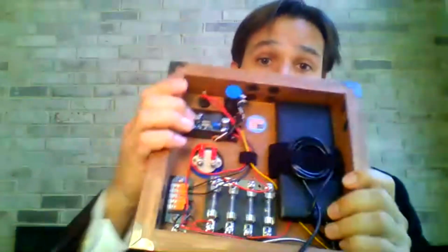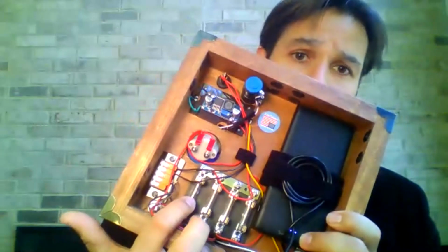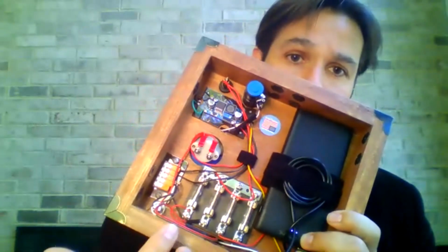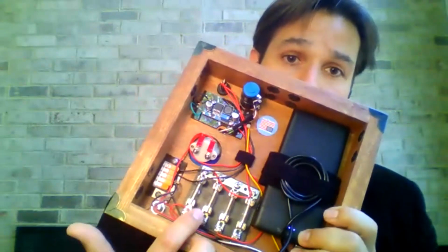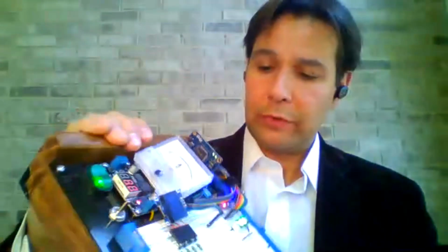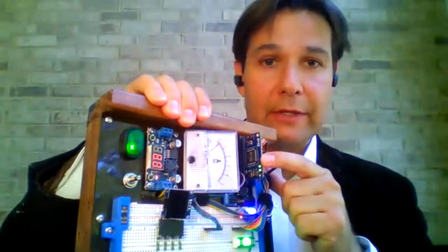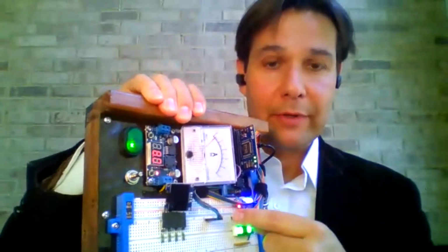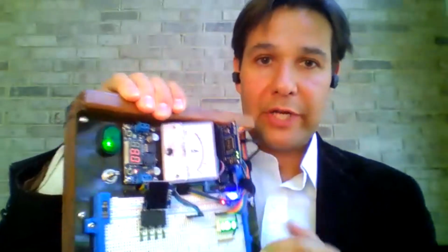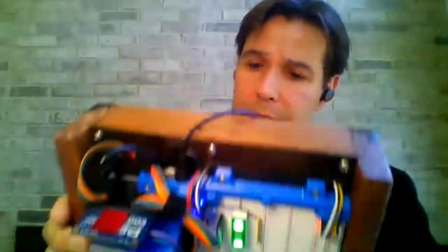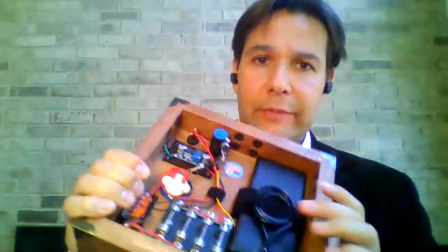Other safety devices, I incorporated fuses on the back for the various branches of the power supply. So there's one for the P2 edge module. There's one for the 5 volts on the board, which also splits off to 3.3 volts, which I had a separate regulator for, because again, I was terrified of them burning up these $50 P2 edge chips. I'd much rather have them burn up a $3 linear breakout board for 3.3 volts. And there is also a fuse for the variable power supply.